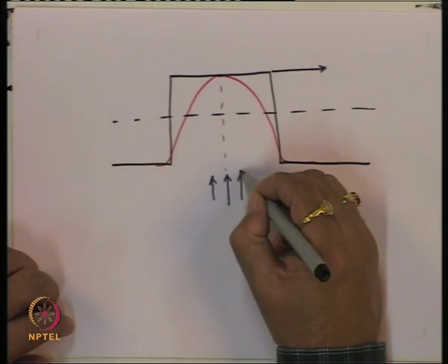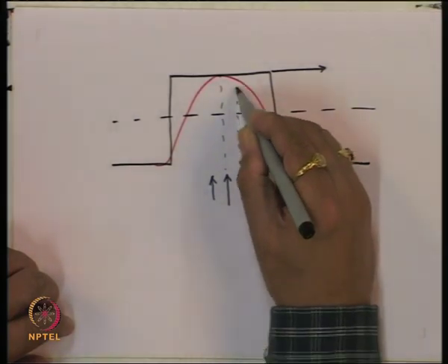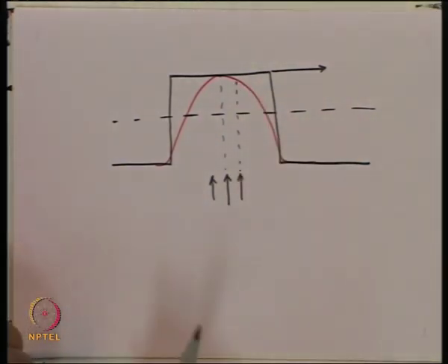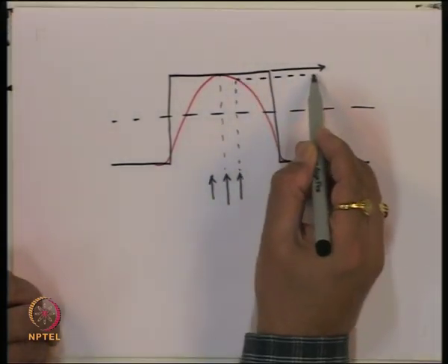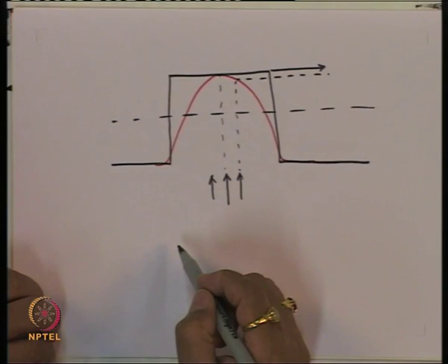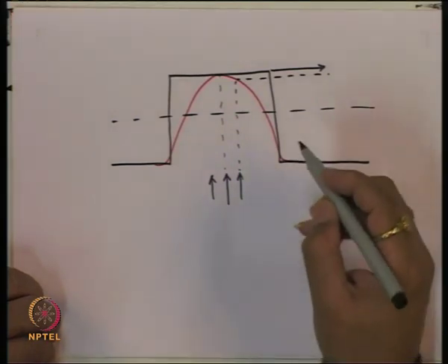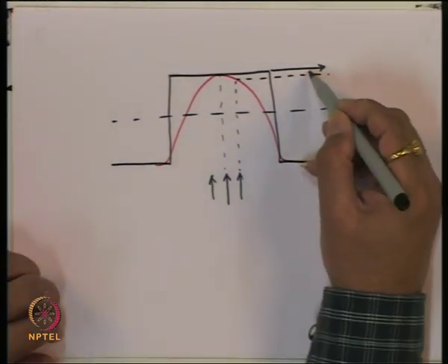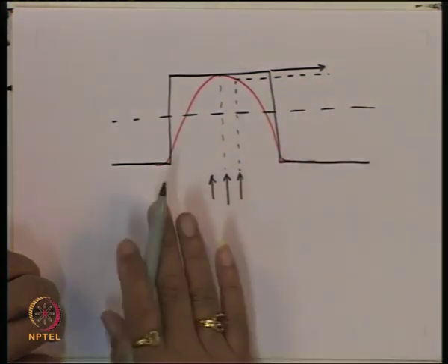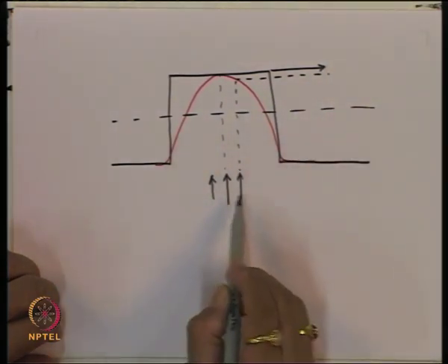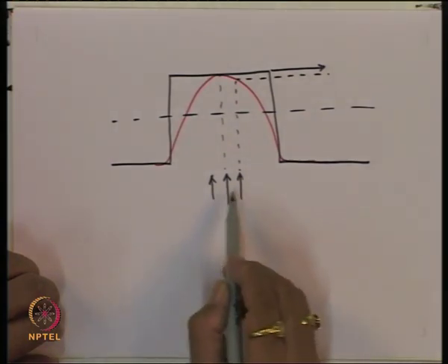Whereas, if we sample here, that means if my clock had drifted little bit, then we sample the amplitude which is this. What that means is now that we are having now a random fluctuation in the intensity or the amplitude of the signal because of the jitter in the clock or jitter in the sampling time.